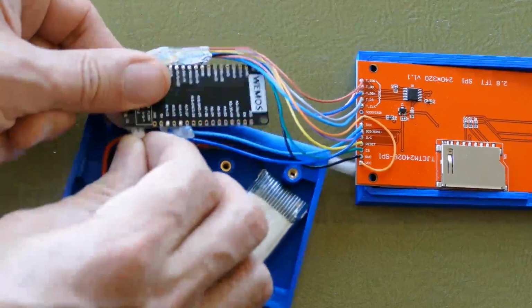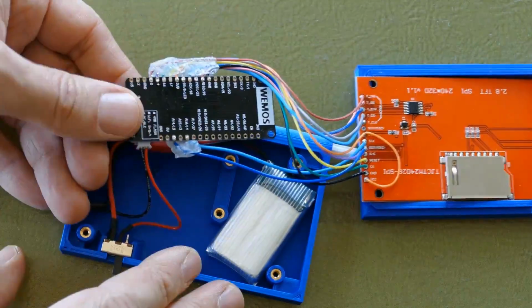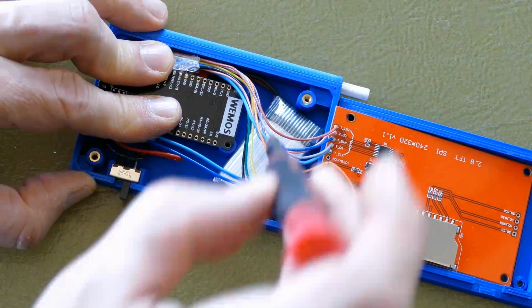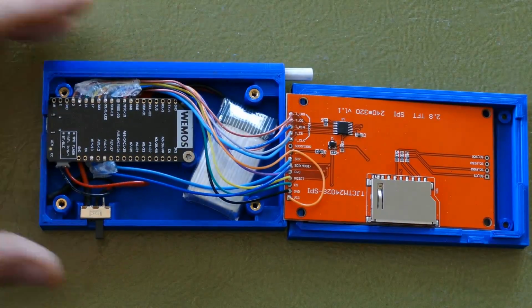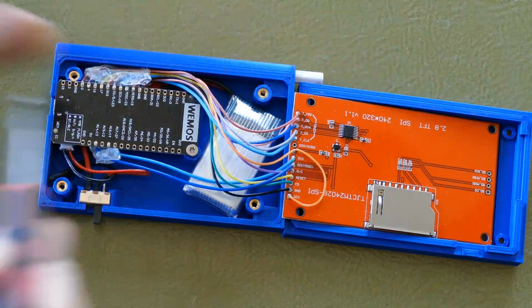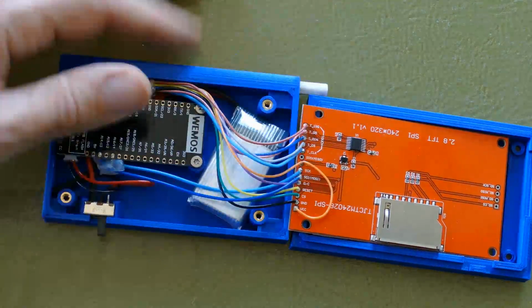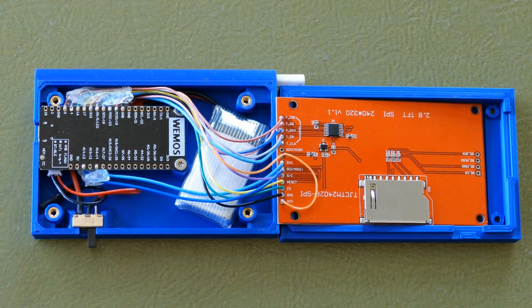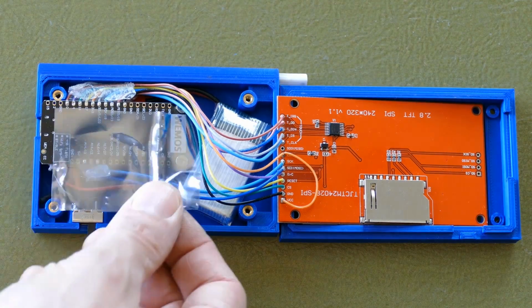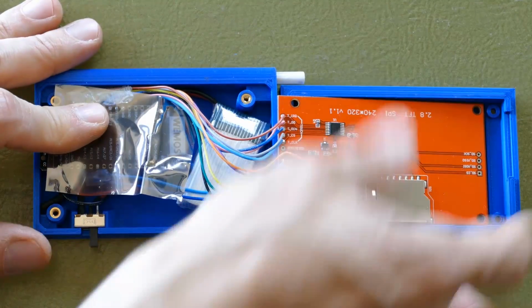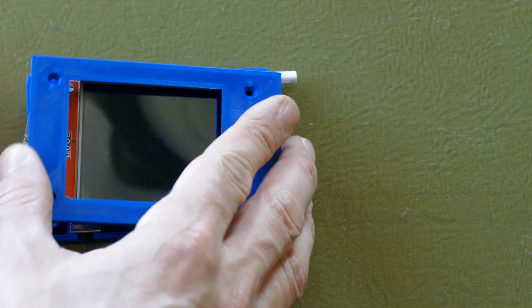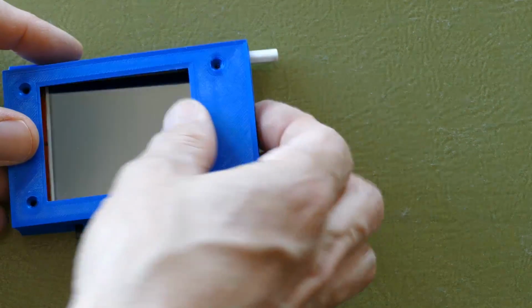The white JST PH plug fits tightly into the battery jack. Two 2.5mm Torx screws hold the board in place. By the way, old hard drives are a great source for small metric screws to secure PCBs. The ESP32 is positioned so the micro USB jack is accessible when the case is closed. It's probably not necessary, but a small piece of anti-static plastic is placed between the boards just to prevent contact between the boards in case someone presses too hard.